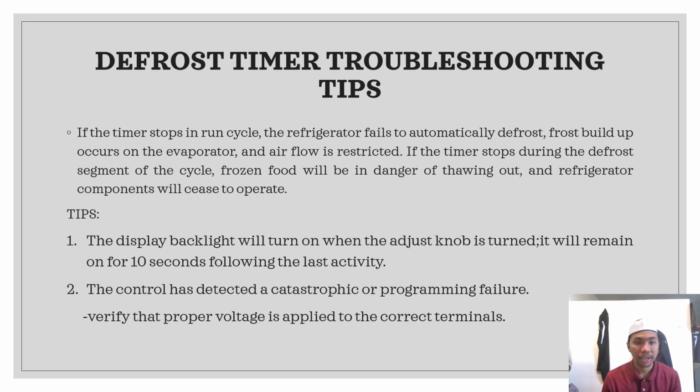Tips. One, the display backlight will turn on when the adjust knob is turned. It will remain on for 10 seconds following the last activity. Two, the control has detected a catastrophic or programming failure. Verify the proper voltage is applied to the correct terminal.